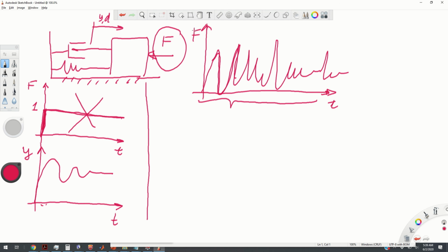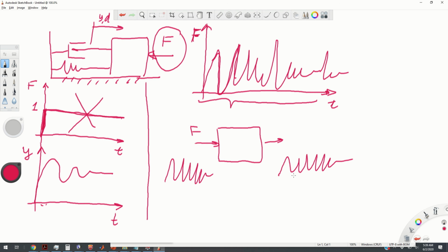But this condition requires that your force has a certain shape, such that when you excite your system and collect the observation data, for example with a random force, your output is sufficiently rich that you can uniquely recover most of the system parameters or most of the system modes.